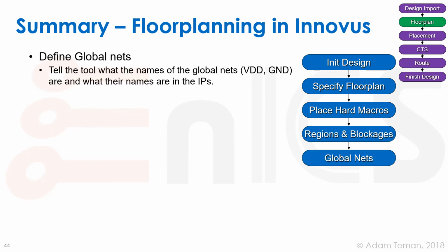So this is a point where we have our design. We decided that our power is called VDD. Let's say this pad over here, we call the net that connects to it VDD, and so we'll have this VDD running all over the chip. But then we have an inverter, and when we look inside the LEF or the lib of the inverter, what we see is that inside it has an inverter here, but it calls this VCC, and this it calls, let's say, VSS,